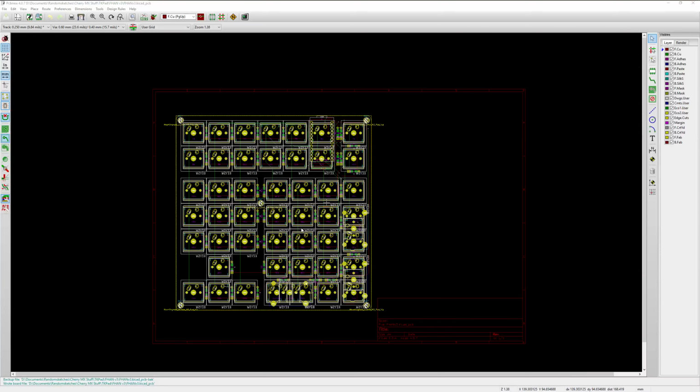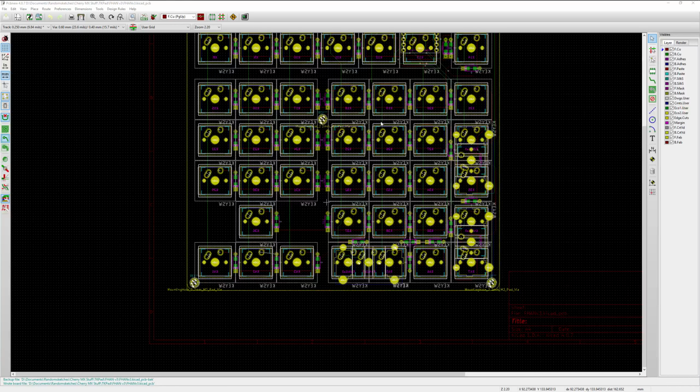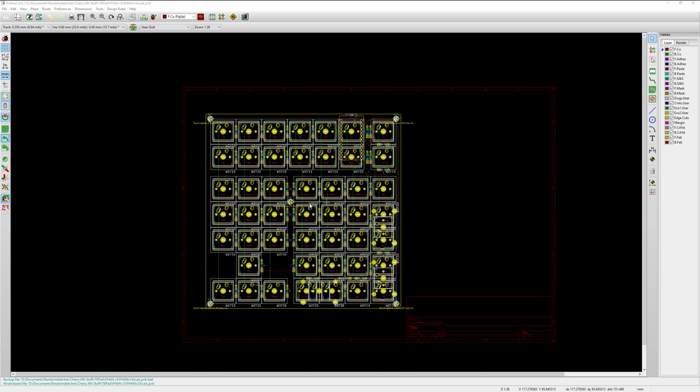So you need to produce a Gerber, but before you produce the Gerber you need to put down your text. You want to put down your silk screen and anything else like that. Otherwise, after you produce your Gerber, it's too late. So we need to insert some text. So here is a text tool. Add text on copper layer or a graphics text, and I want it to be on the back copper,